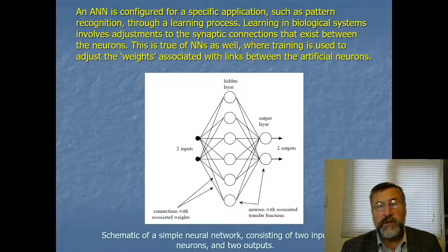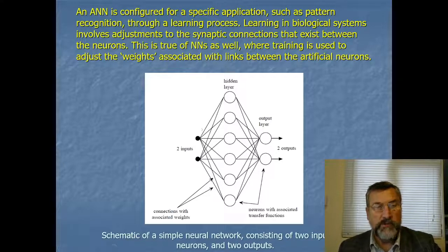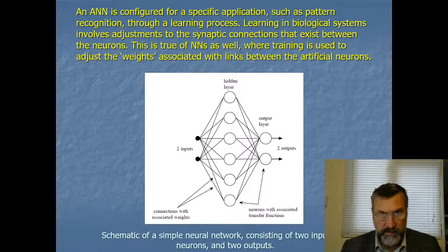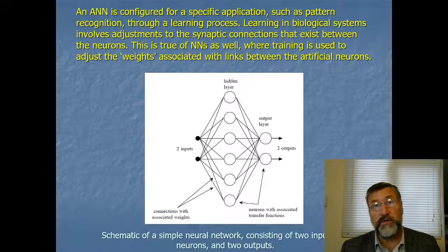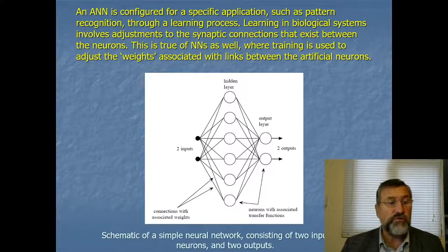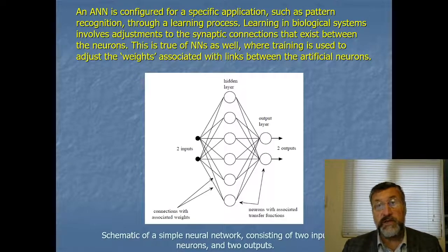And normally, if I'm in industry and I'm trying to model some data, I would probably start off trying to model it linearly. That's typically done, just linear modeling of the data. But the trouble with that is that most processes in industry are not linear. Most are non-linear, in fact, highly non-linear most of the time. So just applying a straight line to modeling something is a bit of a crude and not very effective way of doing it. You can try applying curves to the data you've got to compensate for the non-linearity, and then you could use regression analysis after you apply the curve.